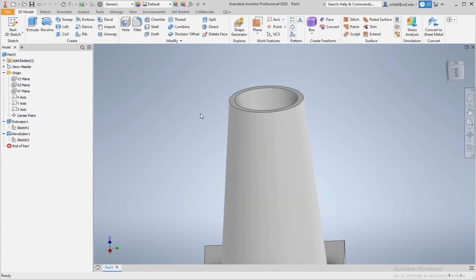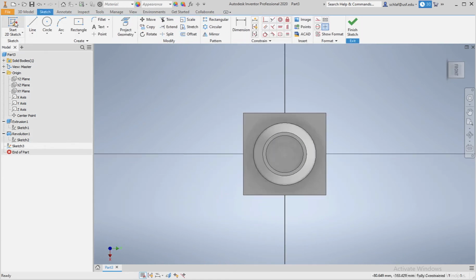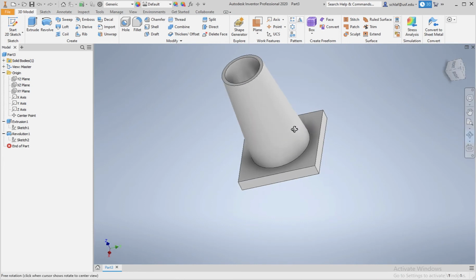Then this tower is wide up here, so we make this with a new sketch, and of course we make it again rotationally symmetrical, so we can again select the XY plane and start a sketch on it. Oh, this was not what I wanted. I selected the wrong plane. So the back button is really your friend in this software. So let's go back to this and select the correct axis.